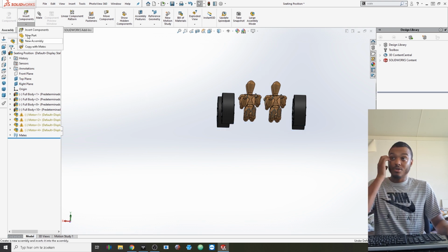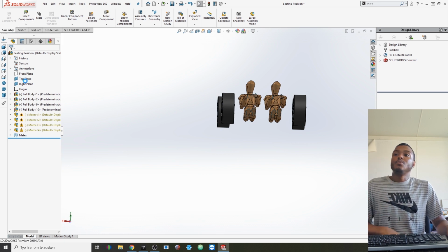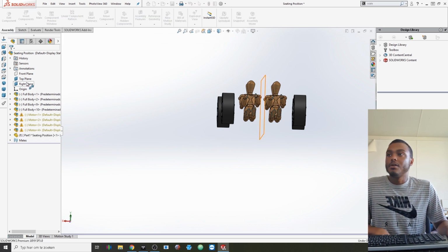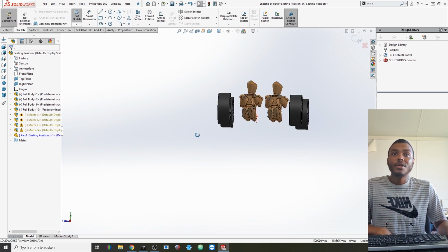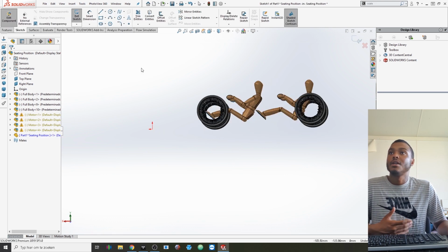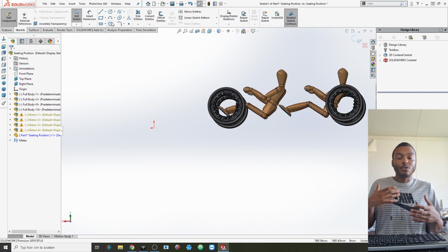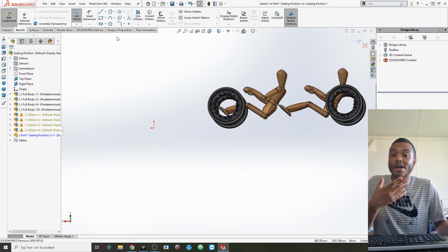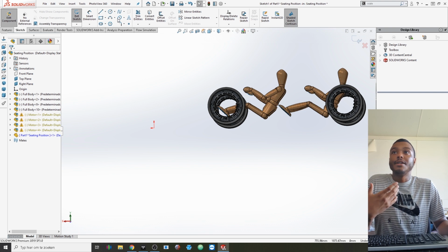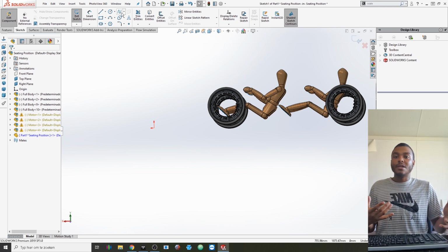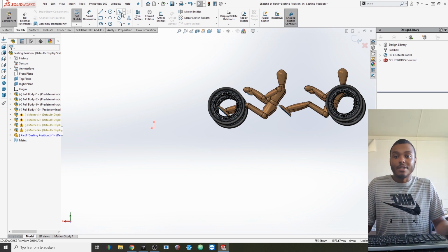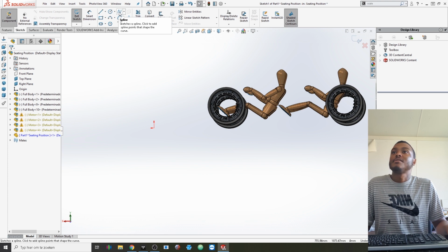So the first thing that we're going to do is create a new part, and we're going to let that new part start from the right plane, because the first thing that I always do when I'm making a car with surface modeling is that I design a roof line, because that will signify how the car will look overall, and it will be a great determining factor. And also a lot of other joining lines that you need to generate the rest of the body will need to attach to that center line. So it's one of the best places to start in my opinion.